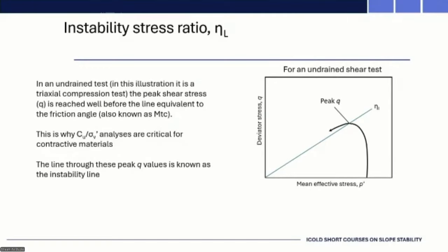That's governed by what's called this instability line, and that depends on void ratio again, and you can approach that instability line under drained loading and probably sit quite happily below that instability line, but a small perturbation can push you towards it and over it. We've even shown, Ricardo Fanni, who's just submitted his PhD using the hollow cylinder device, has actually taken tailings into a stress state above the instability line through very, very careful drained loading, but then a really small perturbation. You don't even see an increase in deviator stress.